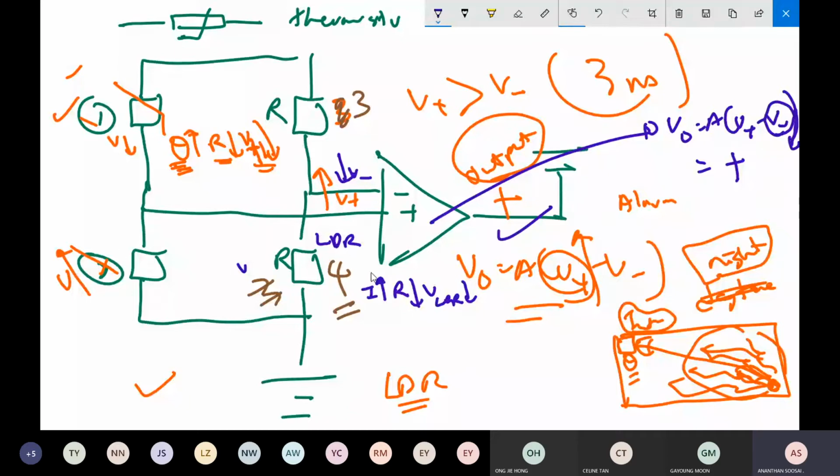So this is the best circuit. The LDR is fixed here, the resistor fixed at the top. This is a good circuit as a fire alarm system. It can sense light intensity and it can sense heat, both, so it can make the op-amp give output. The output will be an alarm, so the alarm will switch on. Any question from here? If you understand up to here, good. I think the main part is this potential divider, the sensors one.